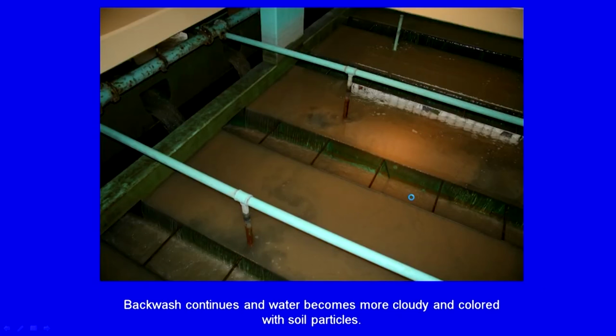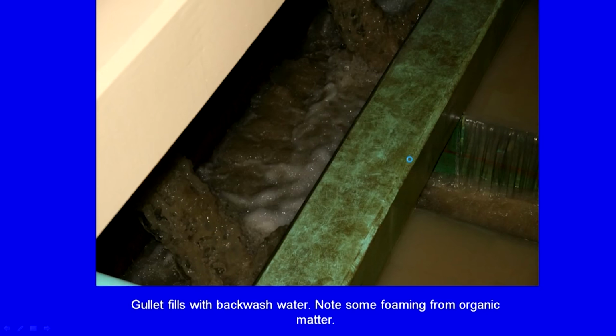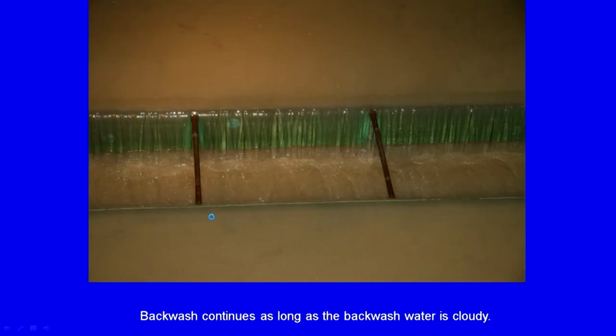And now, as backwashing continues, more of the particles that are adsorbed are going to be desorbed, if I may say so, and they are going to come out here. Backwash continues and the water becomes cloudy and colored with soil particles. That is what you see here, and then it is going to be collected in your backwash troughs. We also see foaming from organic matter, and the backwash water is now relatively cloudy, or pretty poor in quality.